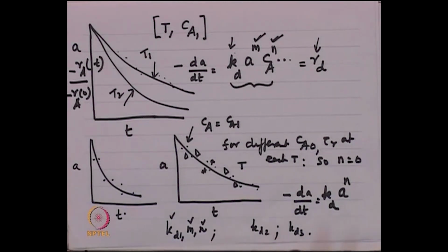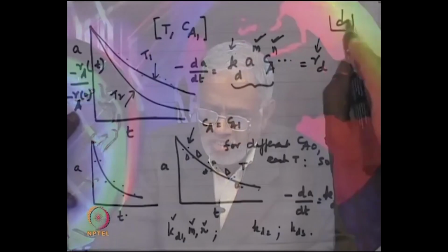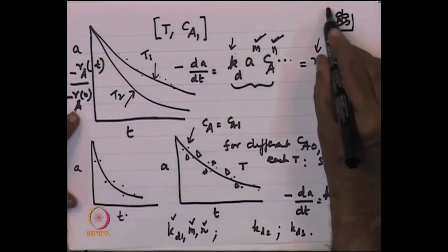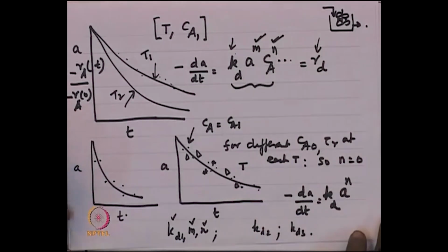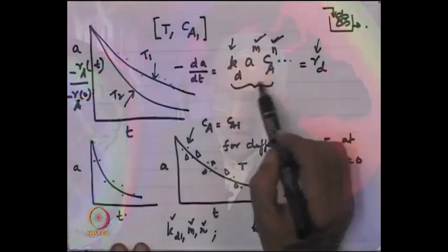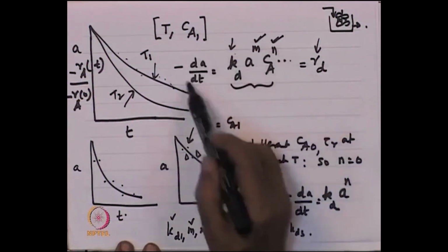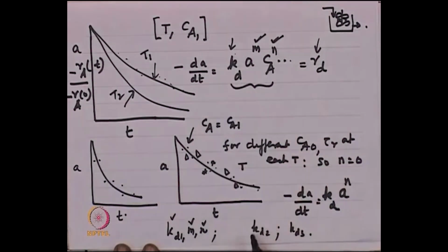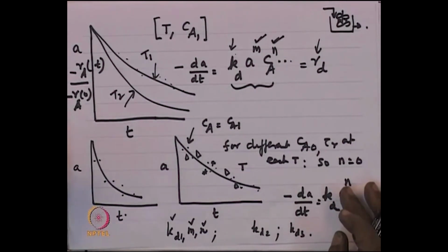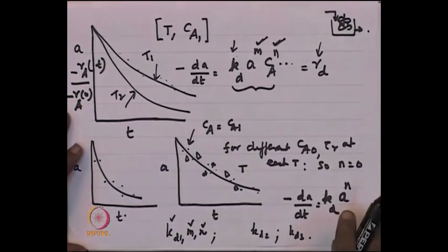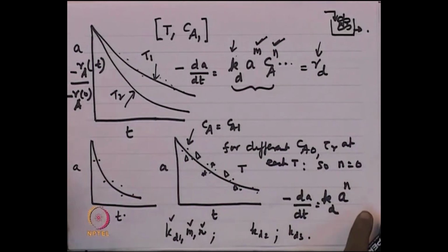Okay. Is this clear? So, the whole object of doing this CSTR kind of experiments is that CSTR allows you to operate at constant temperature comfortably, and therefore, we are able to make composition measurements comfortably, we are able to make changes in the external environment comfortably, and therefore, we are able to get a lot of data which spans a great variety of compositions and temperatures, so that we can fit to this model and find out Kd at different temperatures, find out M and N, and most of the data suggests that M and N values remain reasonably consistent across all these conditions.